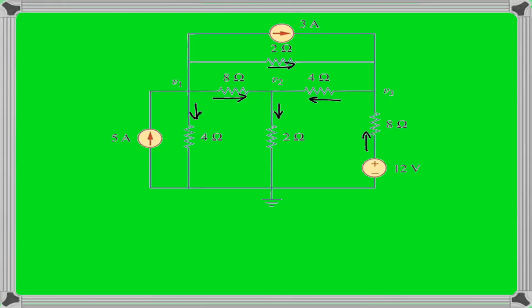Most of the currents are obvious, so we already know their direction, but sometimes it's not very clear. For example, the direction of the current between node V1 and V2 is probably not 100% sure. So you can pretty much guess the direction of the current, but when you start writing equations, you have to follow this chosen direction. You can't say that the current flows from V1 to V2 for the first node and then goes in the opposite direction for the second node. This is kind of an important thing.